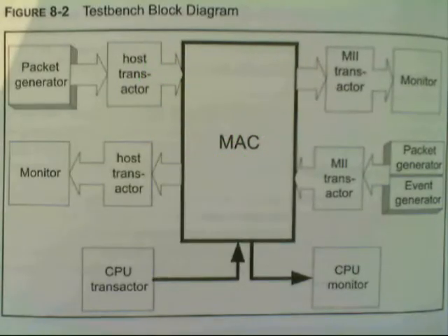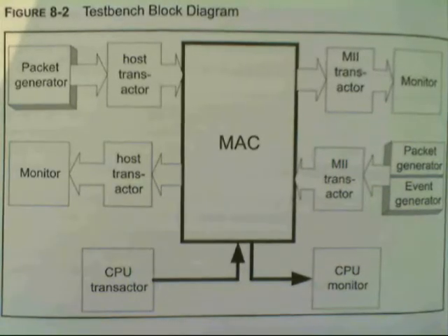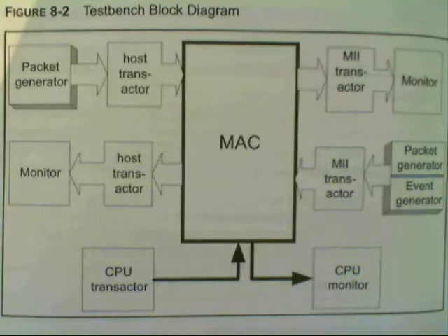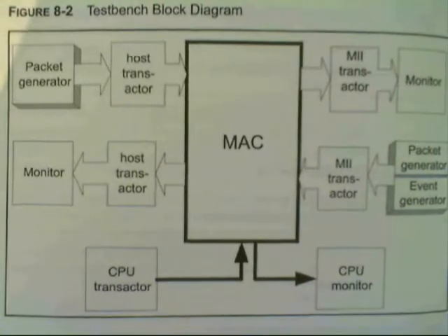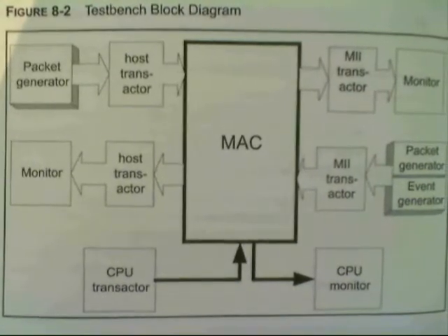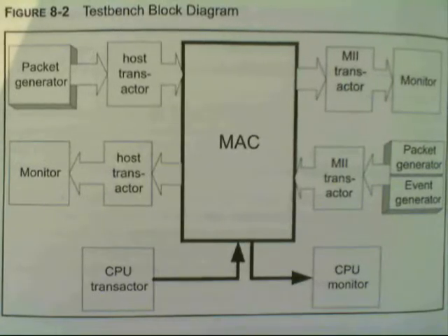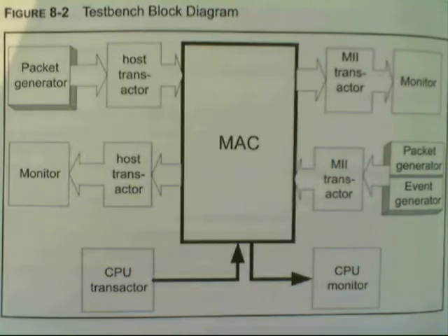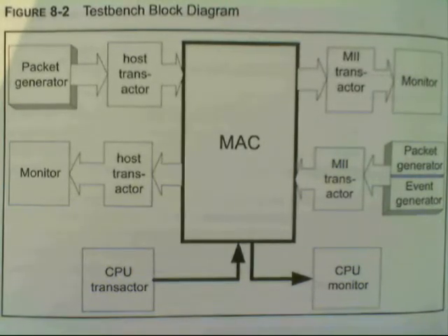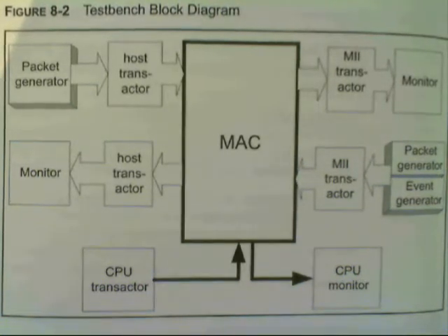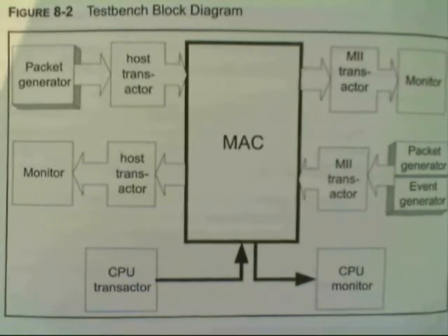Functional verification for the MAC core is performed with an automatic stimulus generation and randomized testing. For stimulus generation for the MAC controller, the test is divided into three categories: normal, transmit, receive with errors. An important element of the MAC verification process is controlling packet distribution, packet size, the MAC destination address, alignment of errors, and CRC error packets.